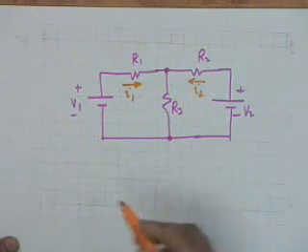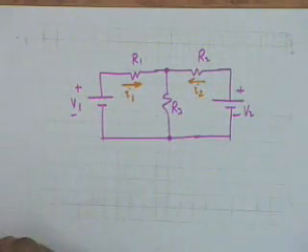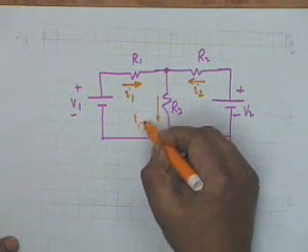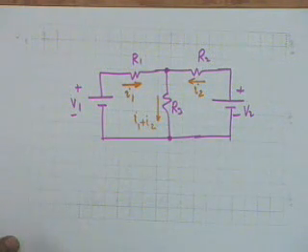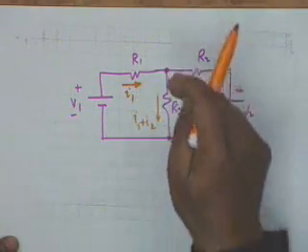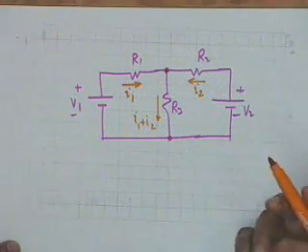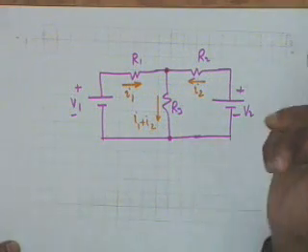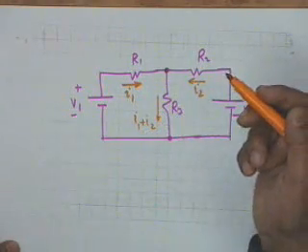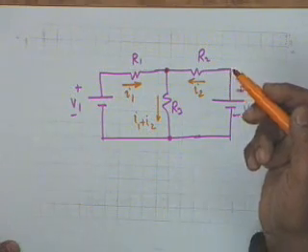One of them is that you arbitrarily assign two currents, let us say I1 and I2, coming out from the two sources. Then obviously by KCL, this current must be equal to I1 plus I2, because this is a node at which two currents I1 and I2 enter, so the current leaving must be equal to I1 plus I2. Now there are two unknowns, I1 and I2, and therefore it suffices to write two equations and solve for them, and these two equations are provided by KVL.